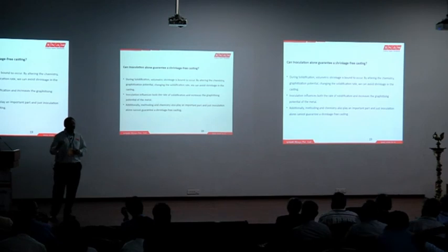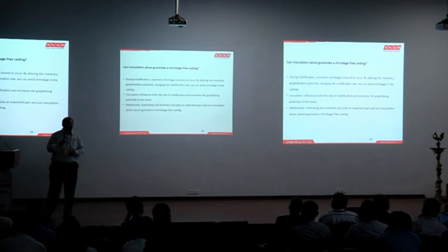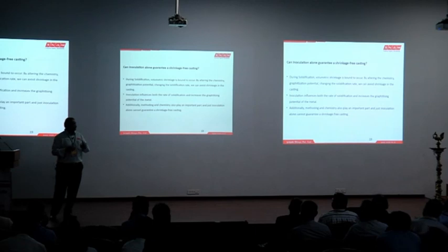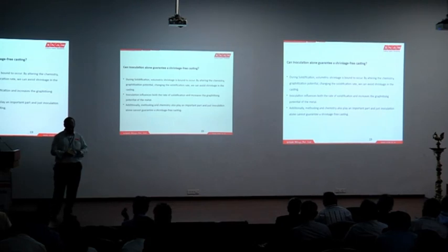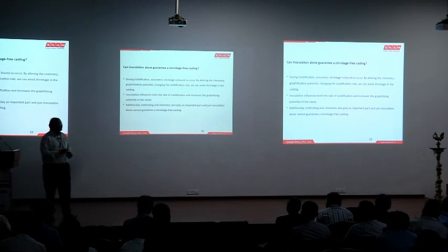Even if you do not add the inoculation, you will still get X minus delta X. But this delta X keeps varying heat to heat, and you might not be able to attribute it directly to any of your foundry parameters. So to avoid this variation, inoculation helps. But a shrinkage-free, void-free or defect-free casting should start with the characteristics of the metal and the foundry itself. That is the methoding, the design, the environment of the foundry or the casting, and liquid metal.